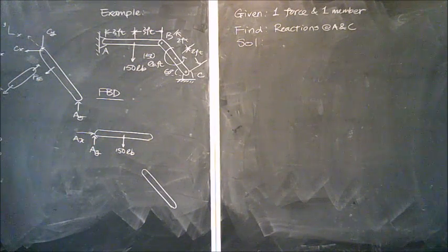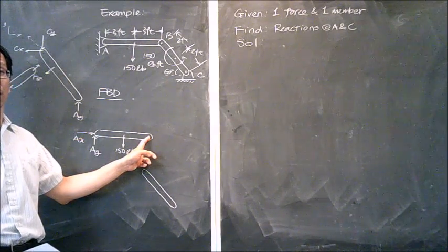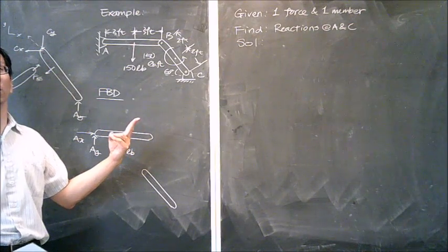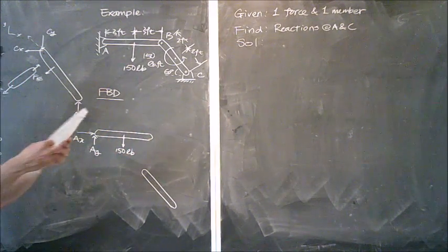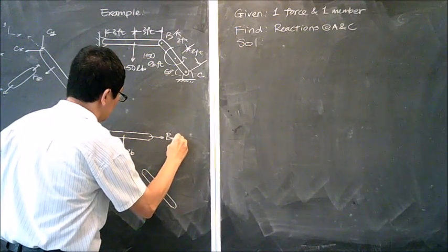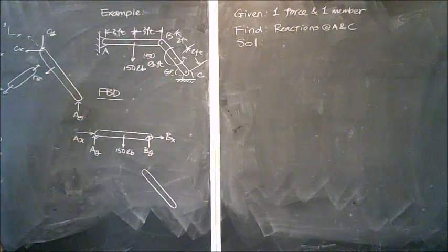Is this a two-force member? Obviously not. So if this is a three-force member or multi-force body, what do you want to put over here? Single force or two force? Two force. Normally we treat that as just X and Y. So in this case, I assume it's going to be Bx, By. There is no reason, because I just want to assume both of them to be positive. That's all.